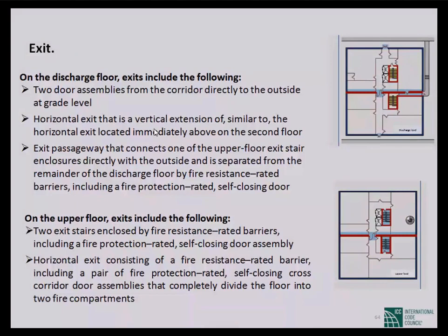Upper floor exit includes the following: 2 exit stairs enclosed by fire resistance rated barrier, including fire protection rated self-closing door assembly. Then horizontal exit consisting of a fire resistance rated barrier, including a pair of fire protection rated self-closing cross corridor door assemblies that completely divide the floor into 2 fire compartments.